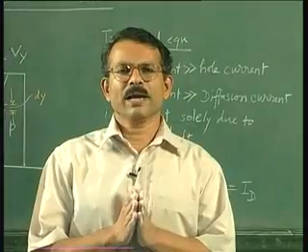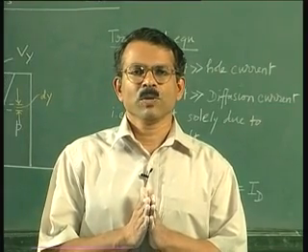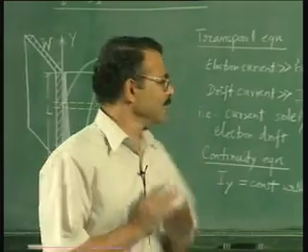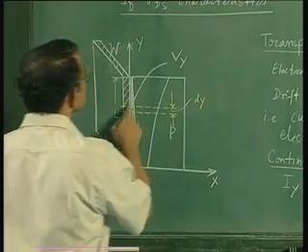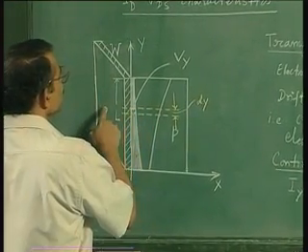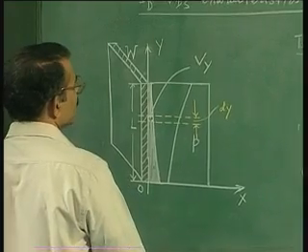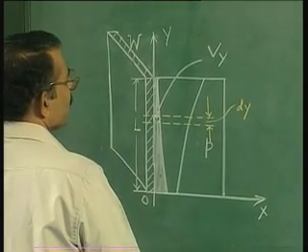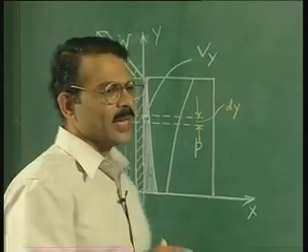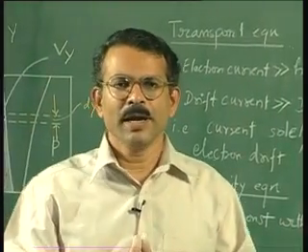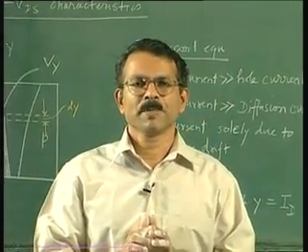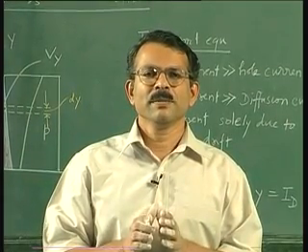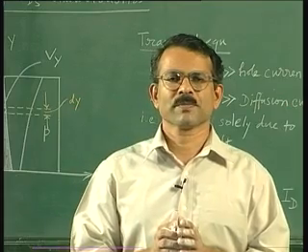Now we are left with the Gauss's law. Where do we use the Gauss's law? The Gauss's law is required to express the charge concentration here in terms of the gate to bulk voltage, because that is a capacitor action. So when you want to express the charge concentration in terms of the voltage, you will encounter again in this case a two-dimensional field and potential distribution.